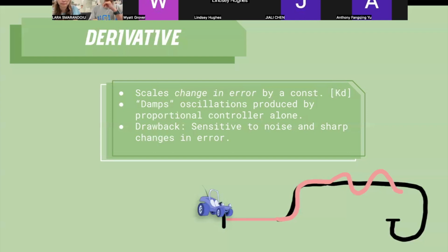That way, if you go 1 inch left, 1 inch left, 5 inches left, it's not going to say five, it's going to be closer to the average measurement. And that way your controller becomes less sensitive to these sharp changes, which is for the better. But if your car does move closer to the track, it'll still be able to track that as well because the average distance will drop over time. And so your car will be able to adjust.